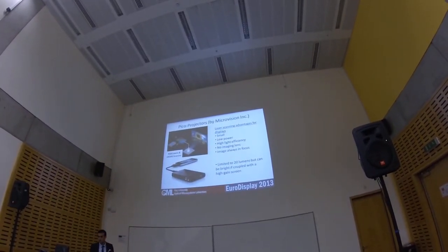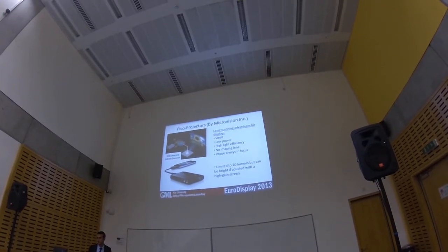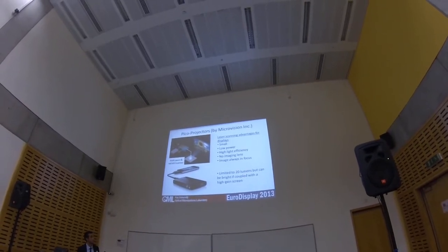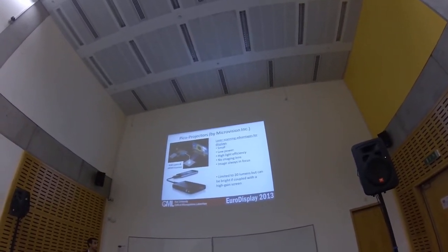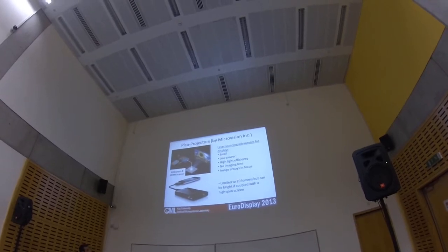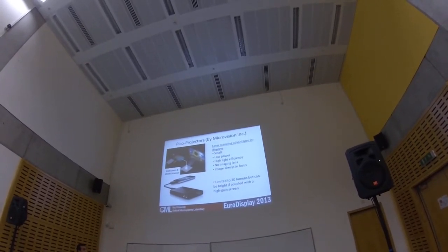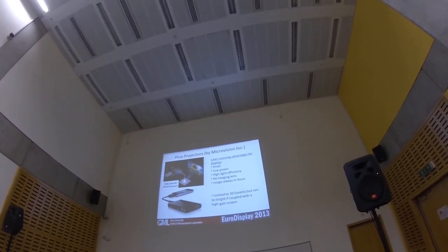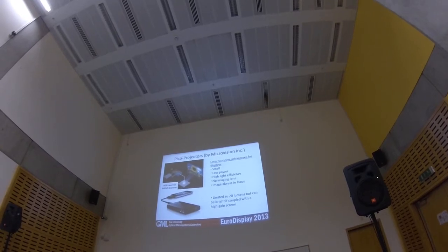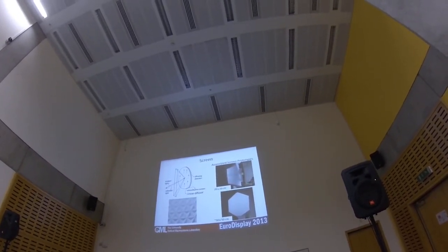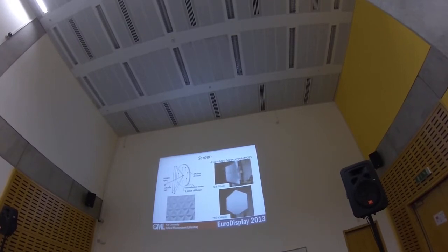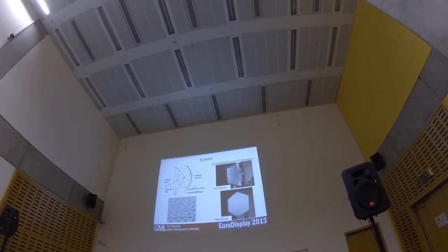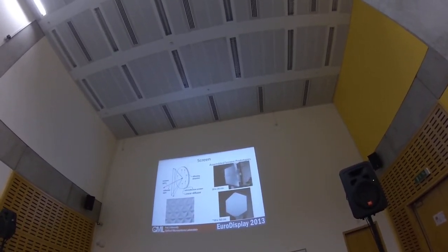The projectors that we have used are from Microvision. They are small and low powered. They have high light efficiency and no imaging glass, so that we can move with the projectors. There is no need to focus. They are limited to 20 lumens, but since we have used a retroreflector screen, we can have a high gain screen, so it's not a problem. The screen that we have used for our project is a retroreflective diffusing screen. The screen consists of a linear diffuser, which diffuses light in only one direction, and the retroreflective screen.